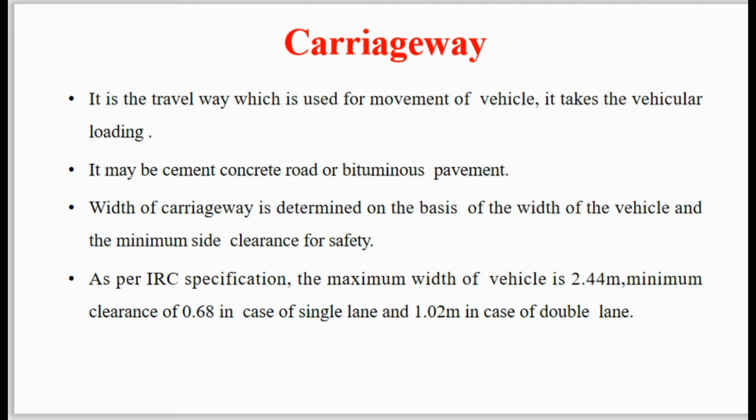This carriageway can be constructed as a cement concrete road or a bituminous pavement, and the width of the carriageway can be determined on the basis of the width of the vehicle and the minimum side clearance for safety. That means the road width required will depend upon the nature of the vehicles moving in the area or the proposed vehicles to move on that road.